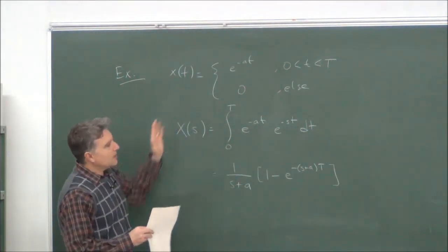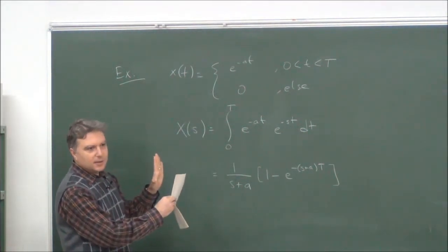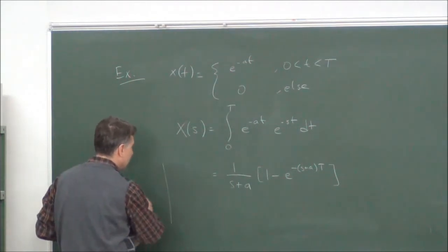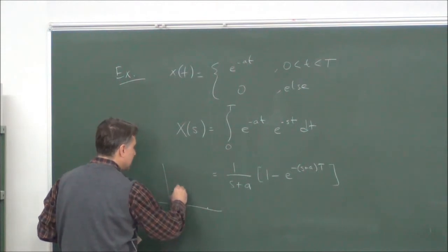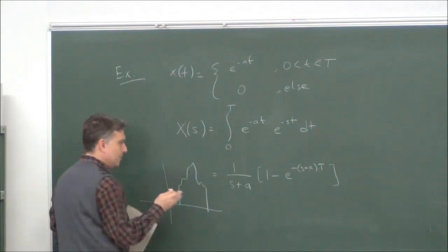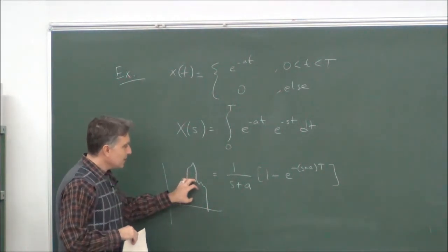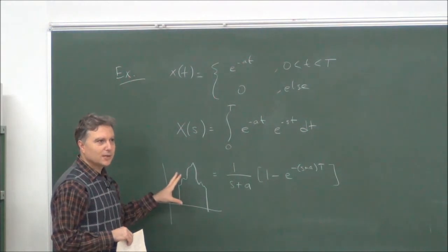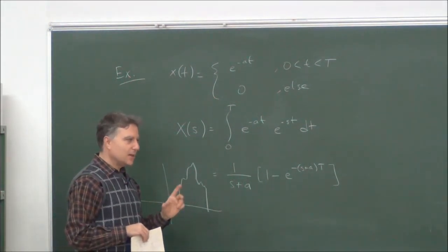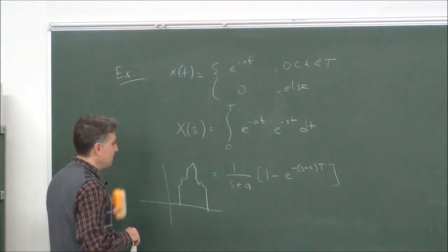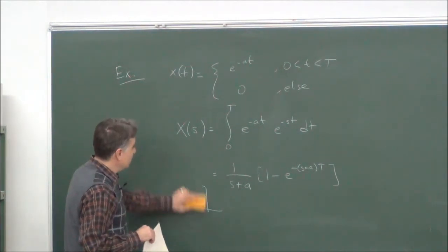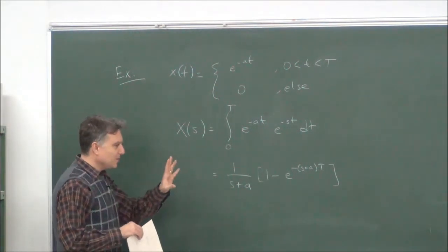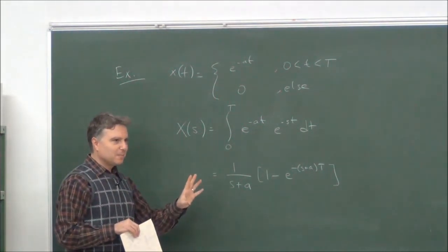The extent of the signal is finite, and within that finite interval, the values are also finite. So it's a signal starting at some point, ending at some other point, whatever that signal may be. This, for example. The Laplace transform of this one will not have any poles. I assure you that. So be careful when you are answering questions in the examinations, for example. Draw the poles and the zeros, for example, I can say. You have to say that there is no pole.